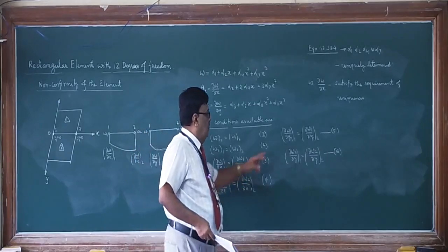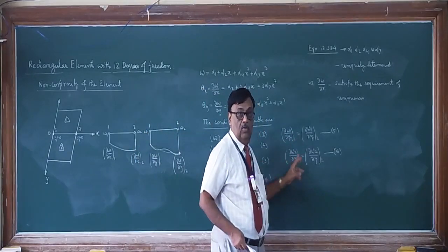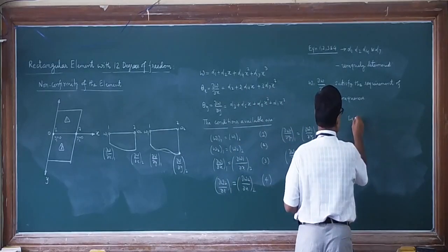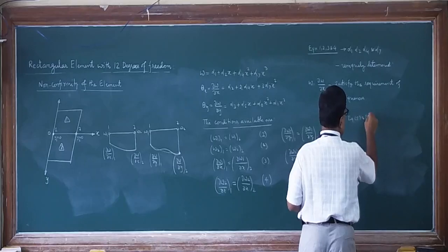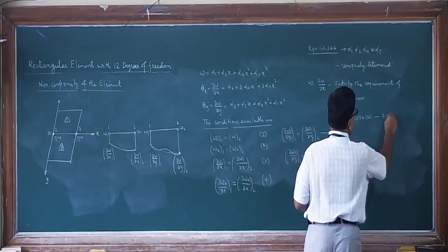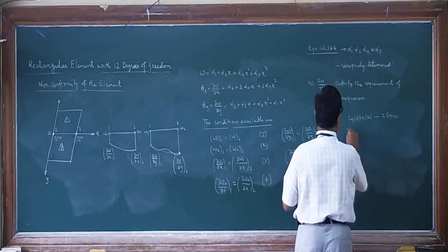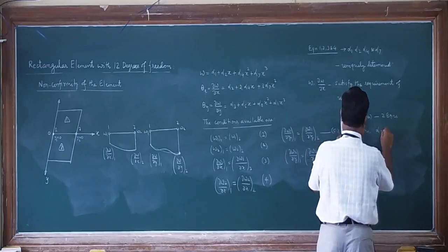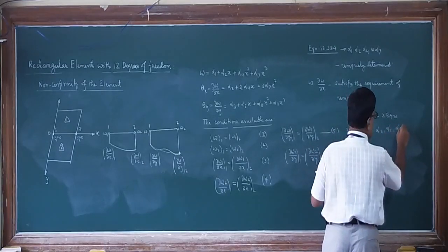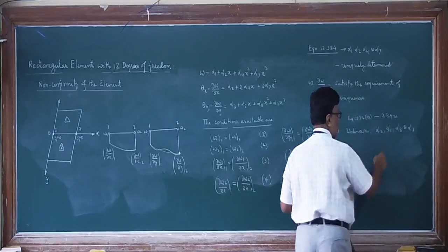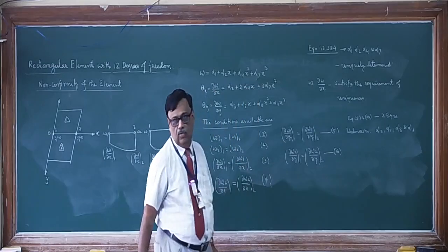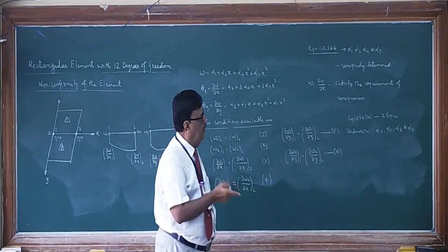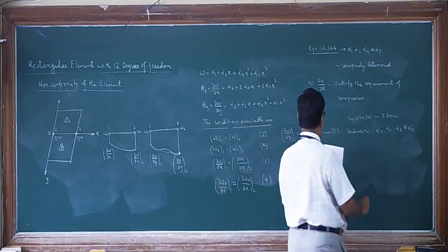Whereas when it comes to the last 2 equations, equations are 2, but unknowns are 4. So what are those? If you take equation 5 and 6, only two equations. What are the unknowns? Alpha 3, alpha 5, alpha 8 and alpha 11. See, that's why it is indeterminate. We cannot solve four unknowns with only two equations. So, there may be a number of possibilities for the values of those. So, therefore, there is no uniqueness.